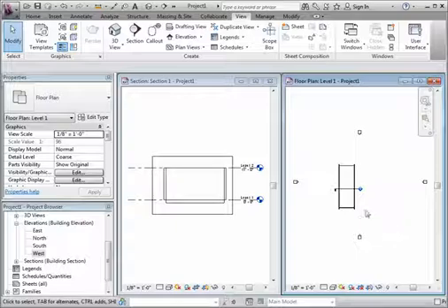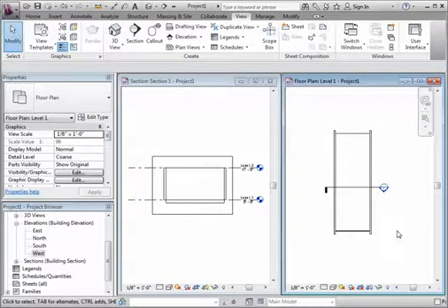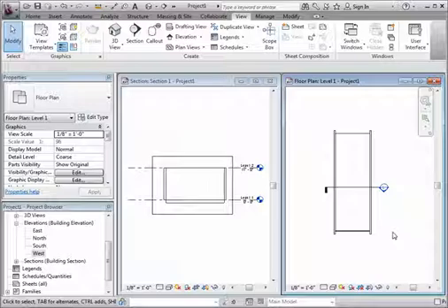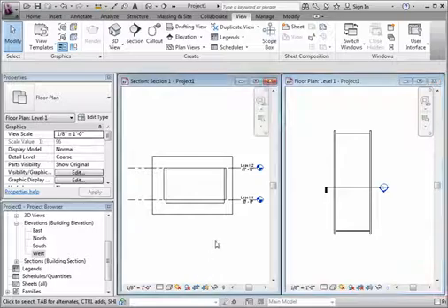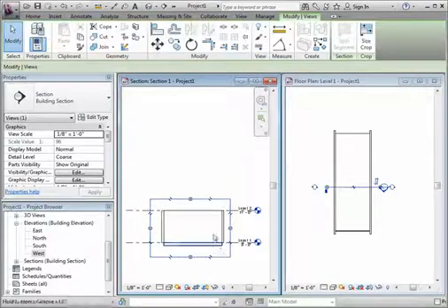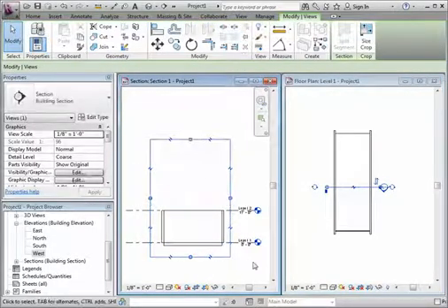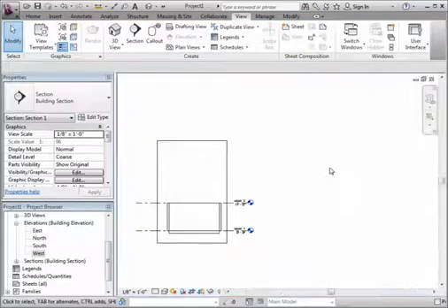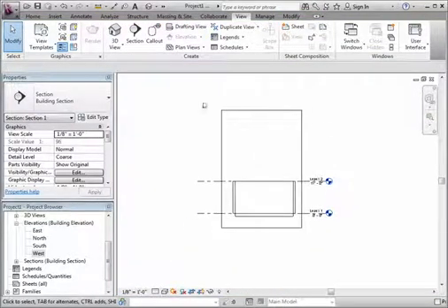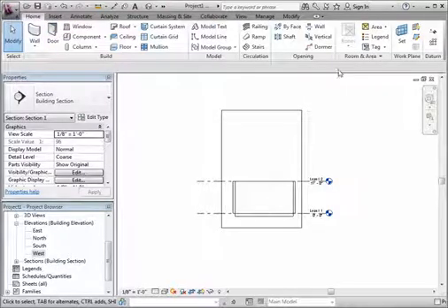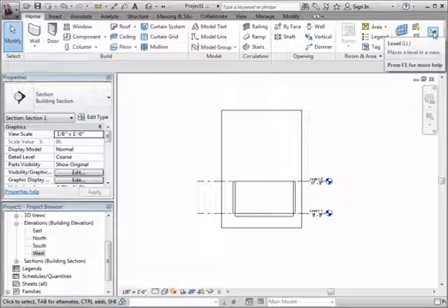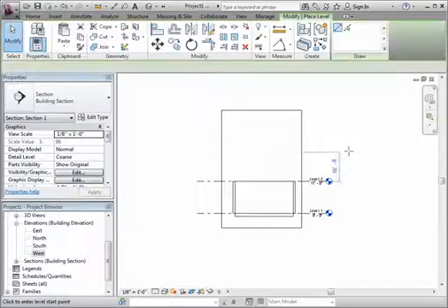Okay, here we are again. So what I want to do next is actually I want to make a second floor of this building. So I'm going to take my section here and I'm going to actually drag it up. And I'm going to make another level. So I'm going to go to the Home tab. And since my screen's a little small, it might be hard to see, but under the Datum tab here, if you go to the top there, you should see the level tool.